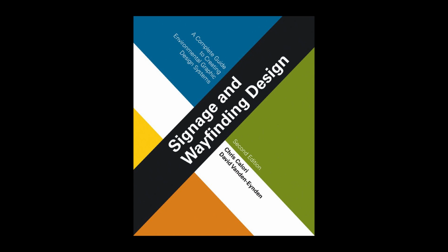The extent and formality of signage technical specs is dependent on the size and circumstances of each project. On smaller projects, the specs can effectively be incorporated into the design drawings. On larger projects, particularly those for large government or institutional clients, the EG designer may be required to provide highly detailed, formalized specs conforming to the master format established by the Construction Specifications Institute, CSI.